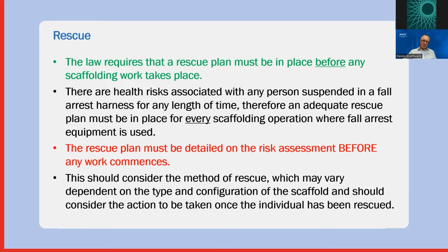We don't want someone to fall and then have to think, now how the hell are we going to get him back? It should be all there. Everything should be planned before we actually get to that position. The rescue plan should consider the method of rescue, and this may vary dependent on the type and the configuration of the scaffold, and it should consider the action to be taken once the individual has been rescued. Again, he may need first aid or even more, depending on how badly he's been injured.